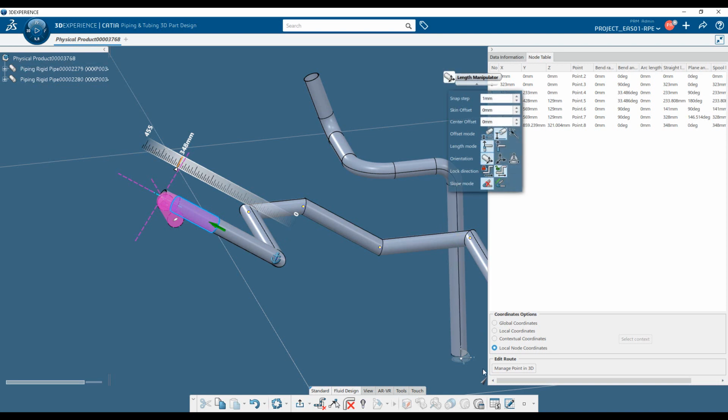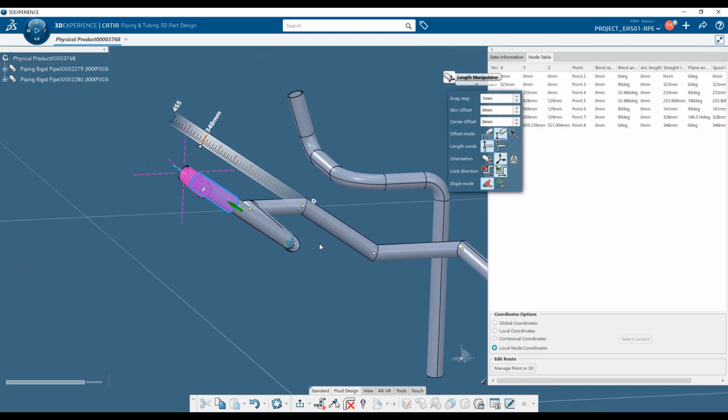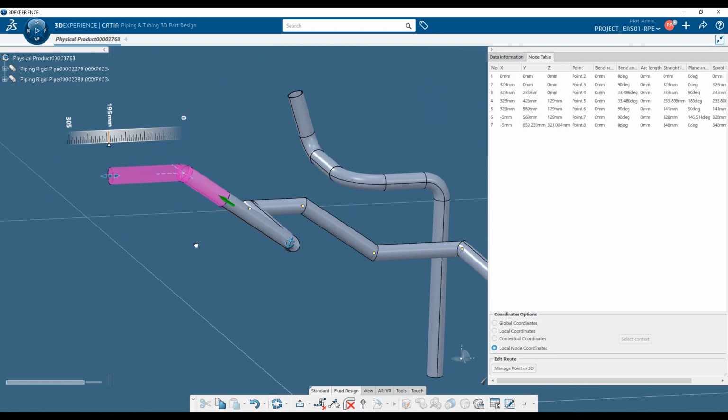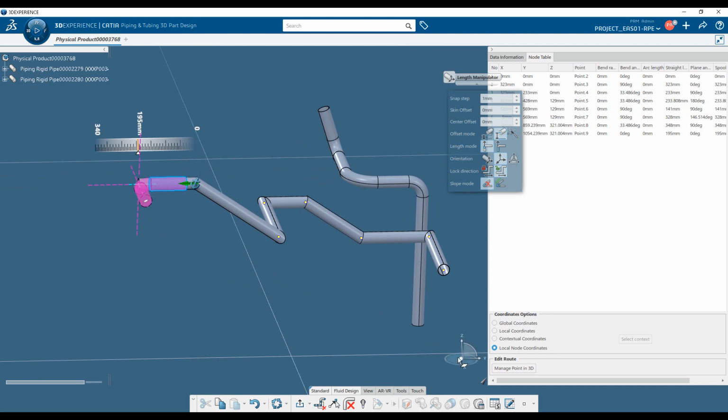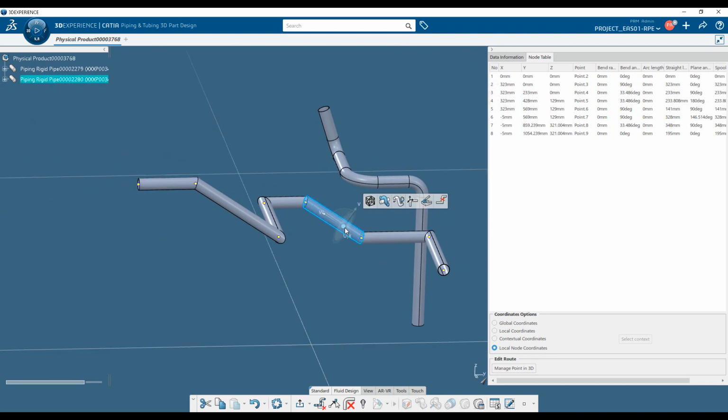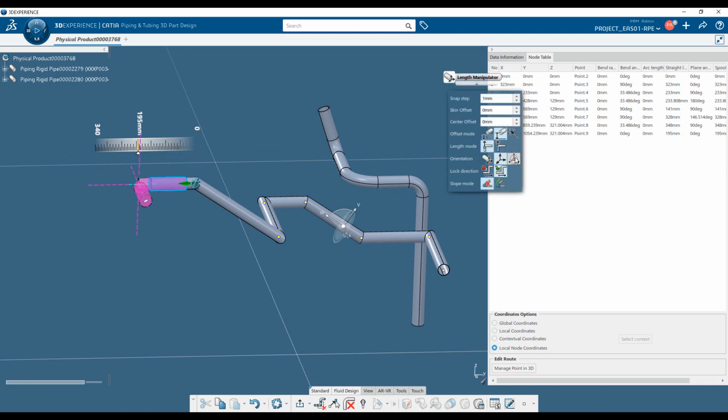If you want to come back to the general orientation of the product, you just select global orientation, like this one, and you can continue your routing. If you want to be in a very specific direction, you can drag and drop your robot on any element and select the robot alignment to compute the dash line according to this position of the robot.